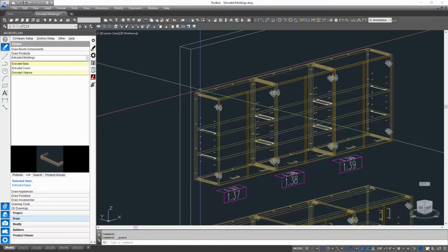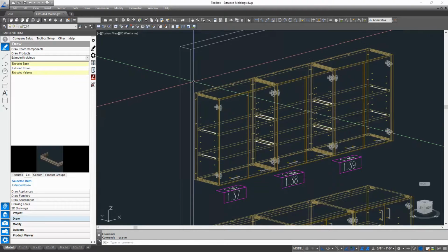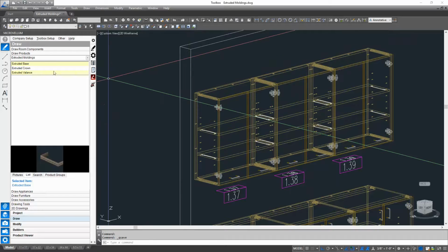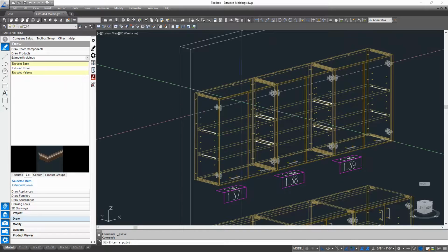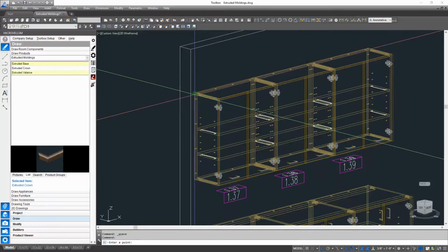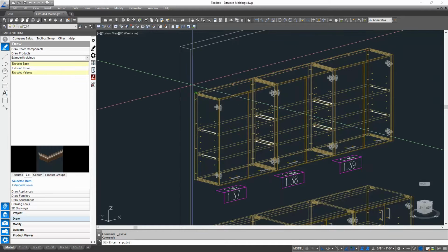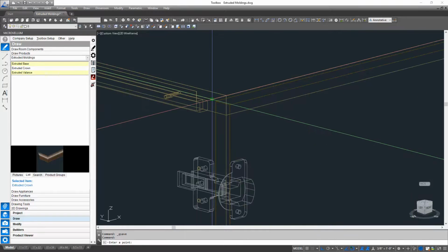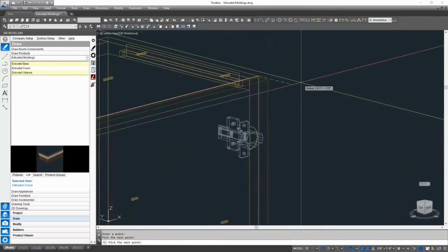In this case, we're going to draw a valance, a vertical valance above this, and it's going to have a mounting strip and a vertical piece, and then a piece of crown on it as well. So we're going to use the extruded crown for that. We can use pick points for extrusion, in the same way that we do an extruded molding from our Draw Room components. We could go around and pick the 3 points for this molding, but we can also just pick the 2 points for the front and then specify that it has finished ends, and it will include that as a single product.